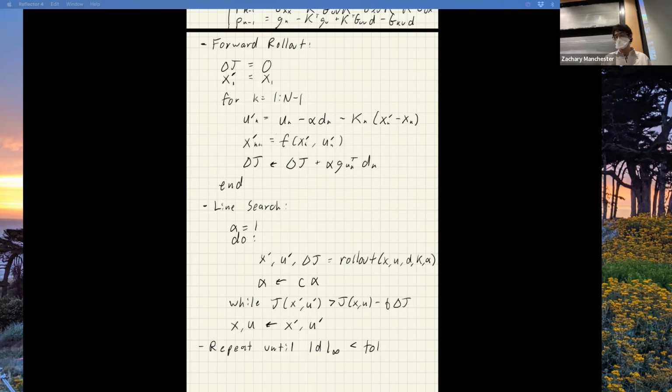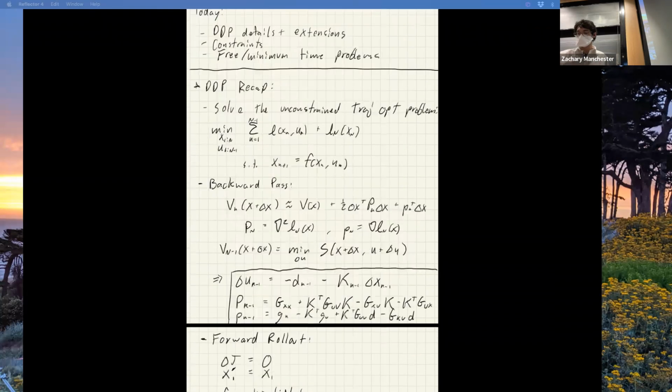Yeah. So what part of this makes it a constrained trajectory optimization? Is it the dynamics are not here? No, so when I said unconstrained, specifically what I mean is it's only that problem right there. There's no additional constraints like torque limits or keep outs or obstacle constraints on the state. So there's no state or input constraints in addition to the dynamics. So it still can handle constraints? That's right. Yeah, it's only can handle that exact problem formulation right there. So you have cost, additive cost function, and dynamics constraints. That is what it solves. If you do anything else, it breaks, right?